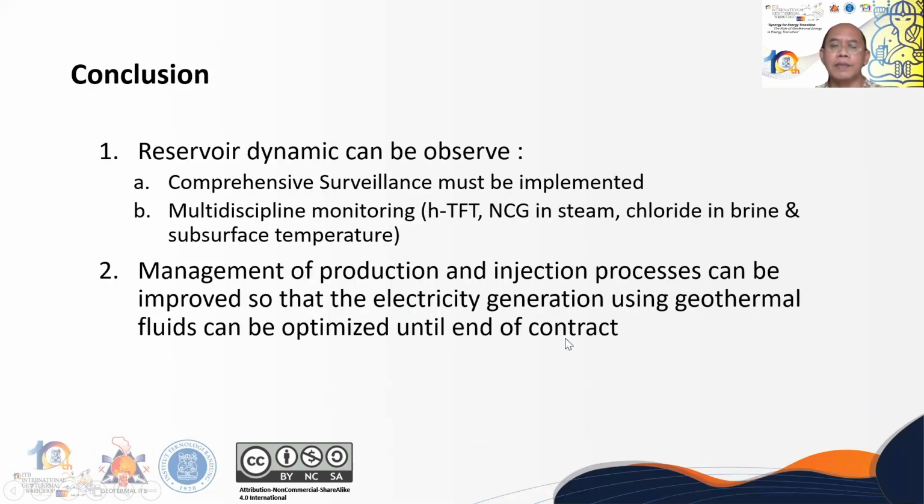The conclusion, first, is that the reservoir dynamic can be observed whenever comprehensive surveillance is implemented, and it should be multidiscipline monitoring such as enthalpy using TFT, NCG in steam, chloride in brine, and subsurface temperature data.